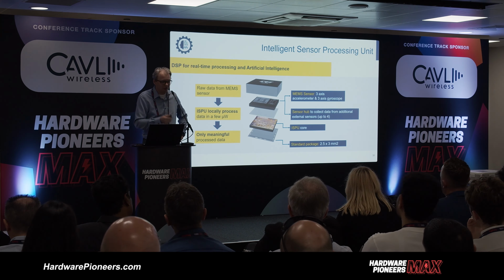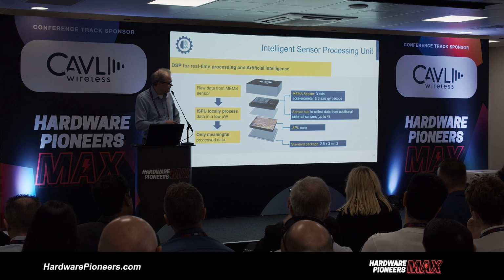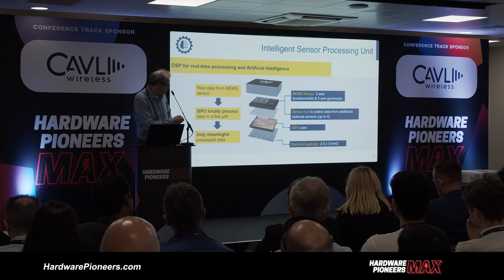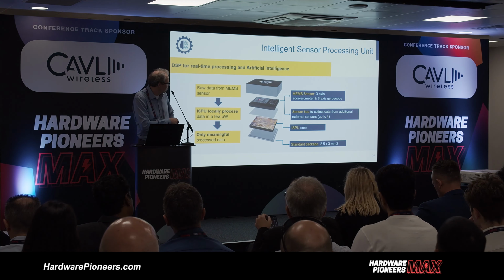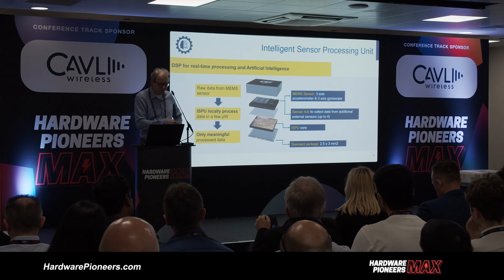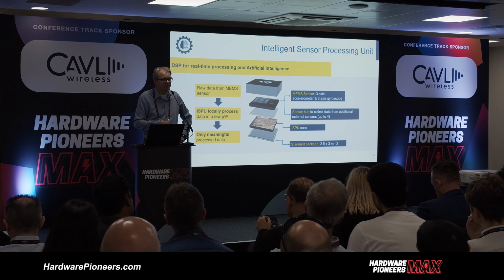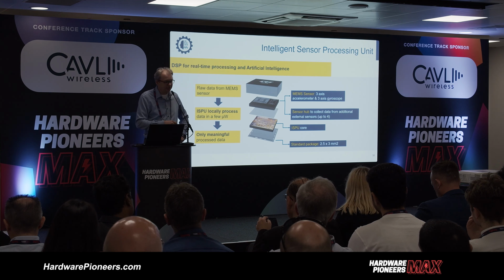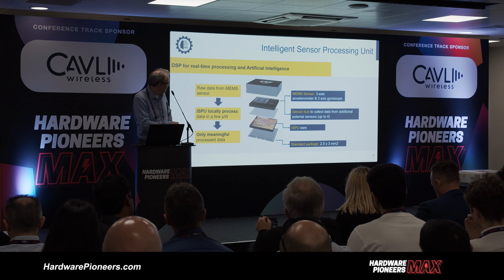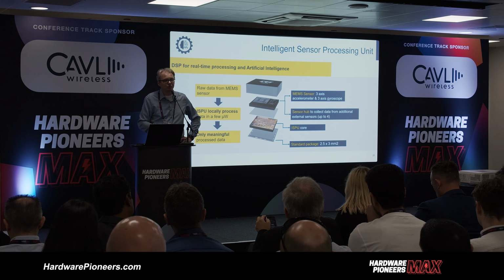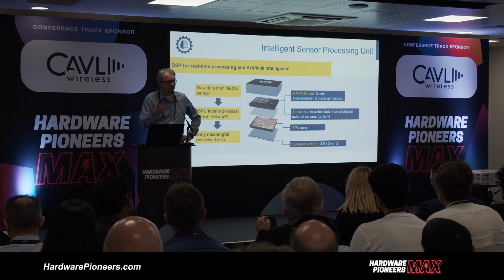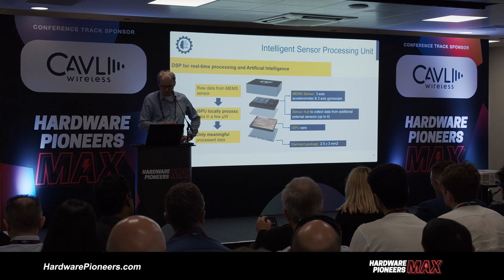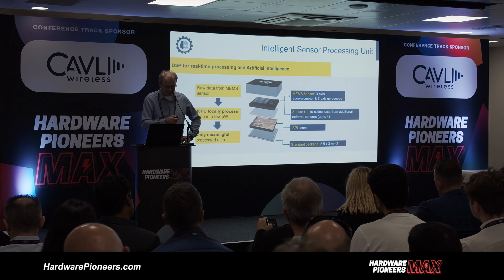Just to show you what it looks like inside, in the sensor components in general, we have this MEMS element. So this is actually the gyroscope portion, and this is the accelerometer portion. And then we have the ASIC, which is doing all the digital processing. And actually this core that I mentioned is located in here, in this same one. So this way we can also make the sensor component in a very cost-efficient way, and also have the very low power consumption that's needed in these applications.